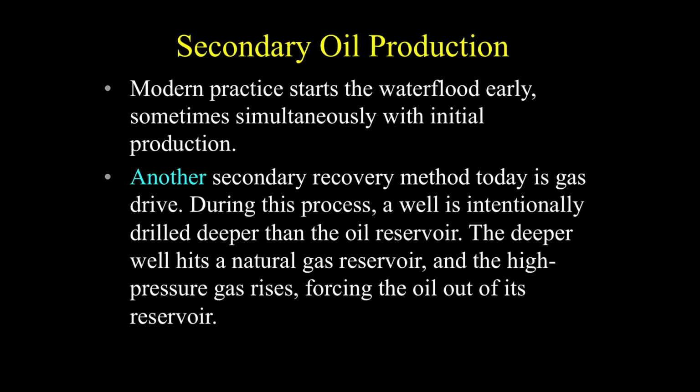Modern practice starts the water flood early, sometimes simultaneously with initial production. Another secondary recovery method today is gas drive. During this process, a well is intentionally drilled deeper than the oil reserve. The deeper well hits a natural gas reservoir, and the high-pressure gas rises, forcing the oil out of its reservoir.